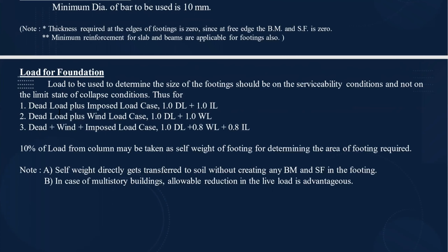Now, these three are the load combinations used for foundations. First is the combination of dead load and imposed load. Second is dead load and wind load. And the third one is the combination of dead, wind, and imposed load.